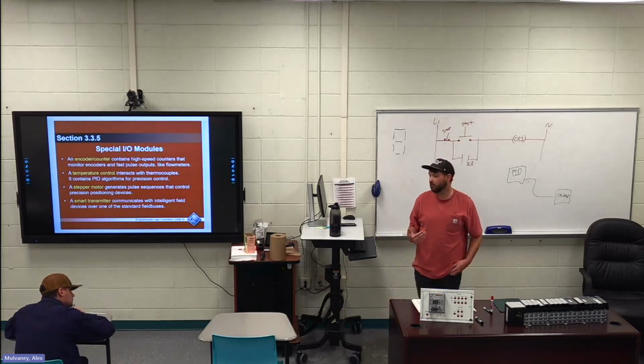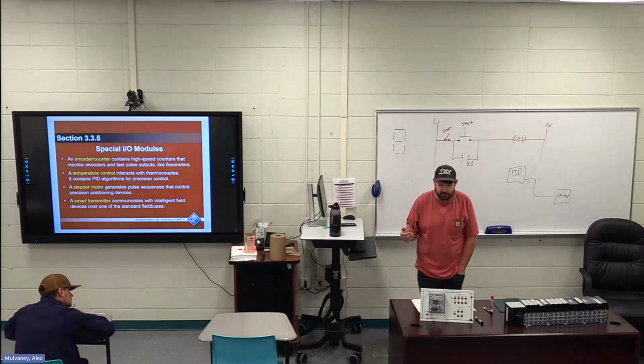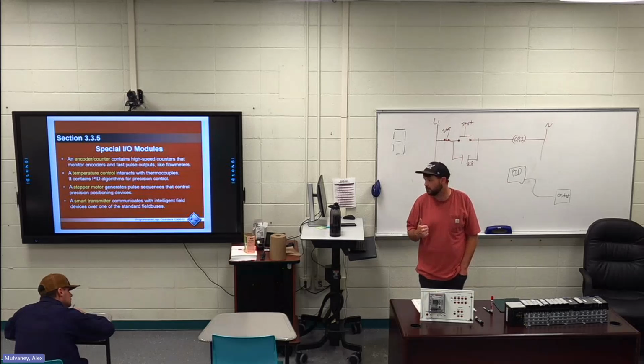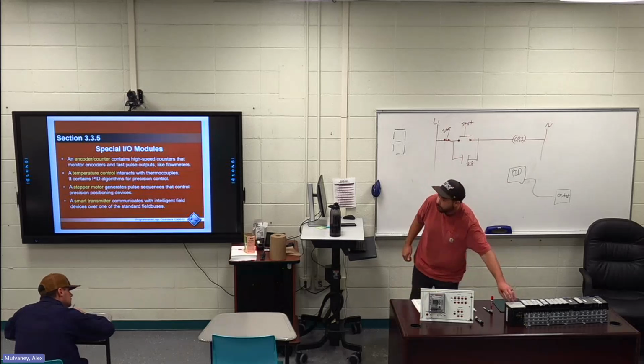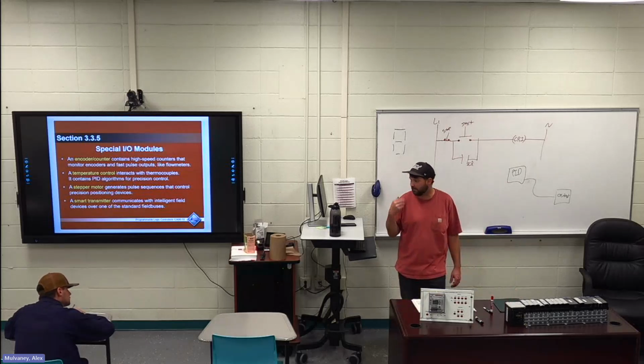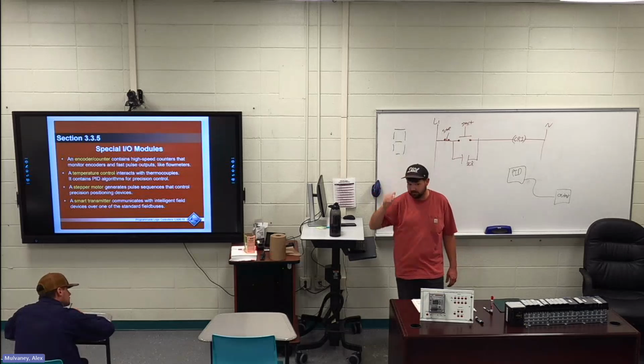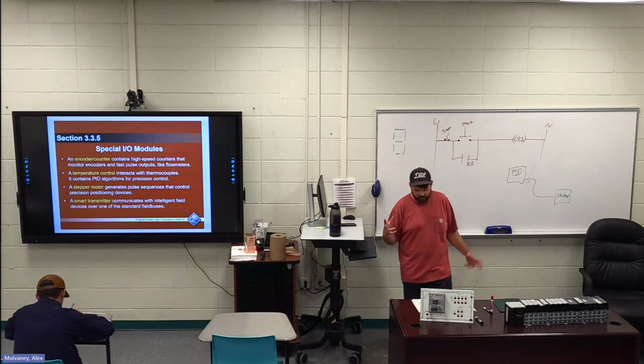That's like, we would run our stuff through a simulator quite a bit, at least the GE stuff. You could run it through a simulator and force stuff to come on and off and make sure the rest of the code worked before you downloaded it into the PLC. I highly recommend that if that's an option for you. It's making sure you don't have a virus in your code, by running it through a simulator.